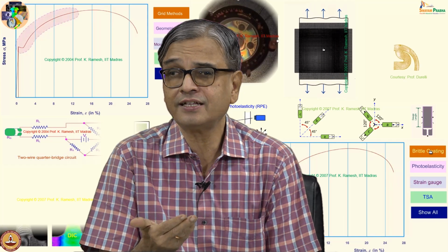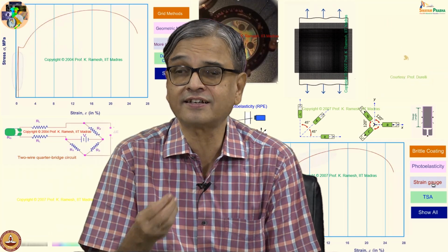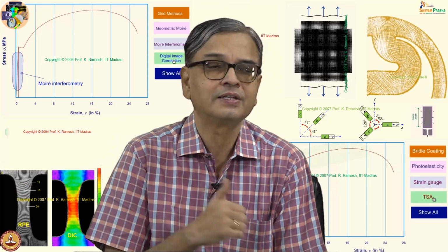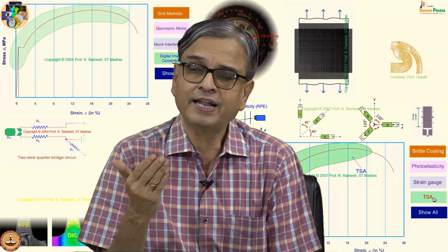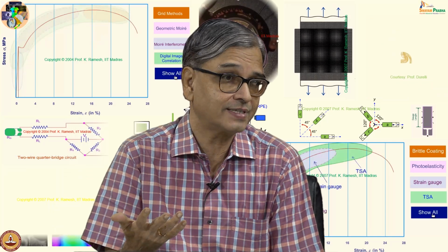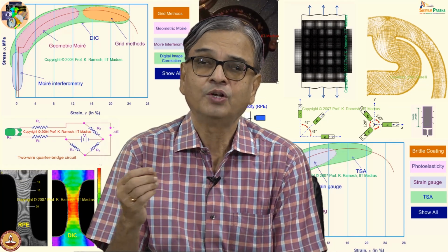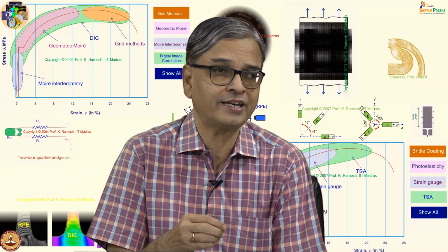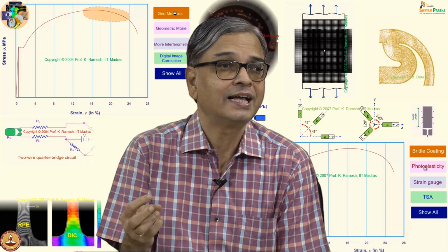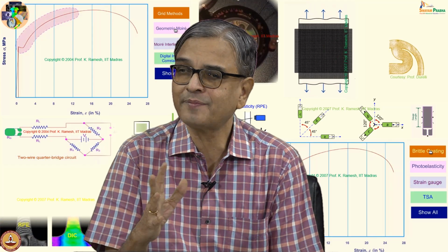Why do you have to study the strain sensitivity of a wire? We have to understand why you make a strain gauge as a grid. Why do you not have a simple speck of material to give you strain? That is one issue. Another issue is, when I want to paste a strain gauge on an object, a priori I do not know what the level of strain is. Is the idea clear? It can go from the elastic region to the plastic region. When I want to interpret the data from the strain gauge, whatever calibration constant I use should be the same for elastic as well as plastic ranges. Otherwise, I cannot make a measurement.